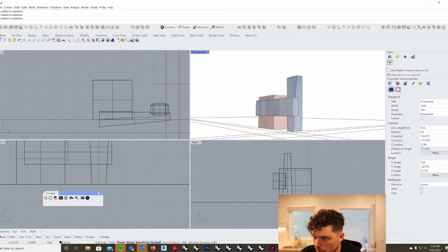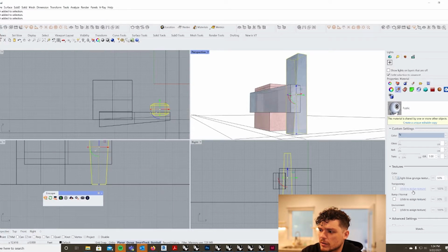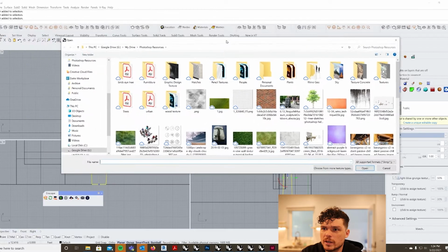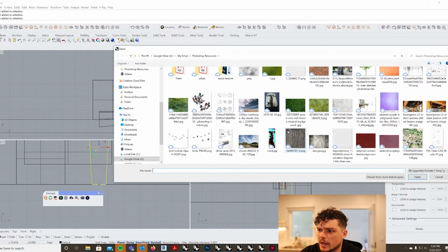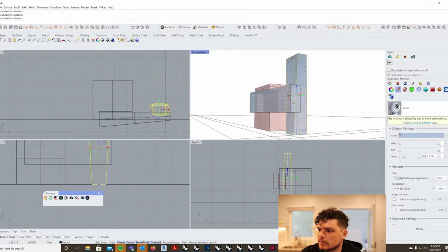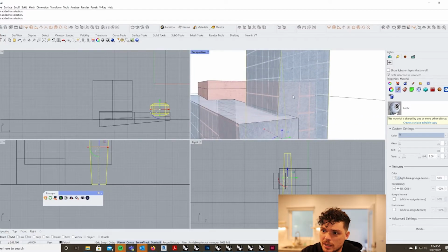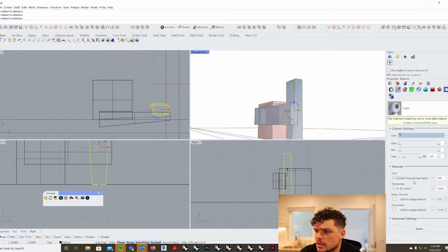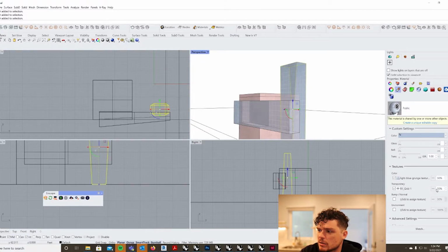The next thing that we can do is start to apply transparencies to this. So for instance, I tend to look for stuff that is black and white. I could use this grid for transparency, and you'll notice that it's starting to apply this grid to it, and that could start to imply mullions. Then I would come in here and reduce that size, reduce that intensity so it's not as obvious, but it could start to inform what could eventually be mullions.